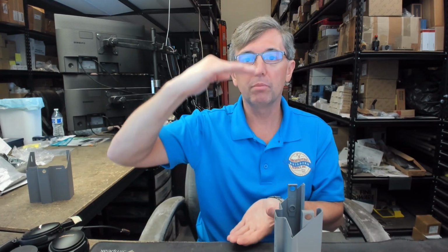So a very common question when it comes to drywall frames is what rough opening size to leave. Generally 3/4 inch here, 3/4 inch here, and 3/4 inch here is perfect. I've not encountered a manufacturer who requires a different size. So a 3070 is going to be 37.5 by 84 3/4: 36 plus 3/4 plus 3/4 is 37.5, and 84 plus 3/4.